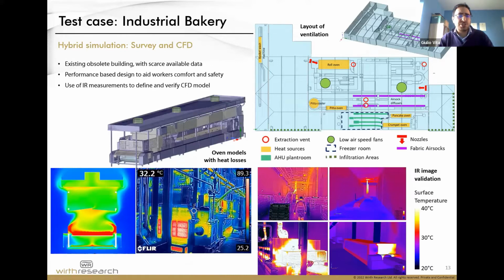Another test case which is of interest, I'm trying to be as fast as I can, is an existing industrial bakery. Being existing, the problem is that normally there is a lack of data associated to it. So in this case, we didn't perform dynamic thermal modeling. What we did instead was we went in there and measured the surface temperatures using IR methodology.